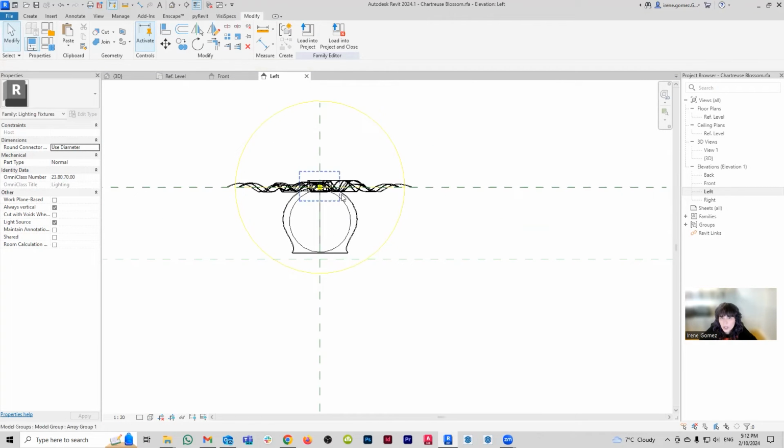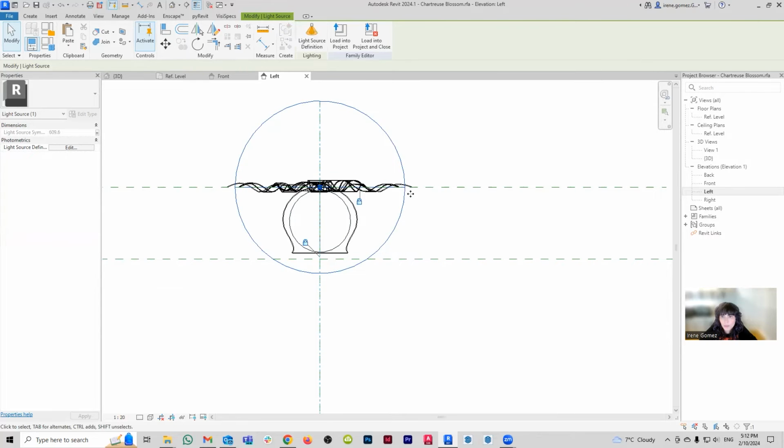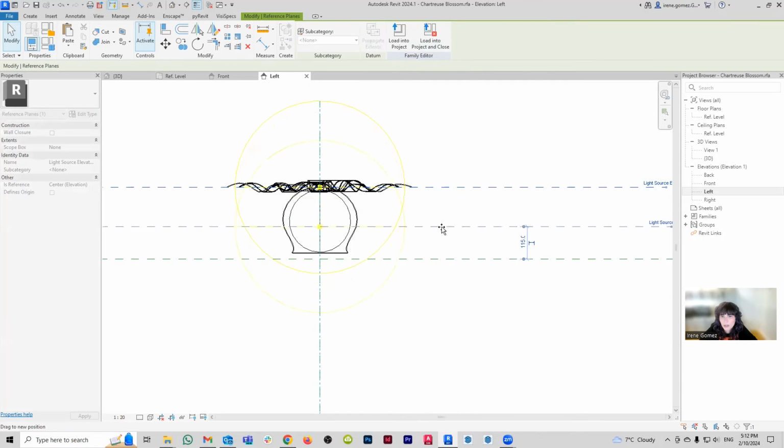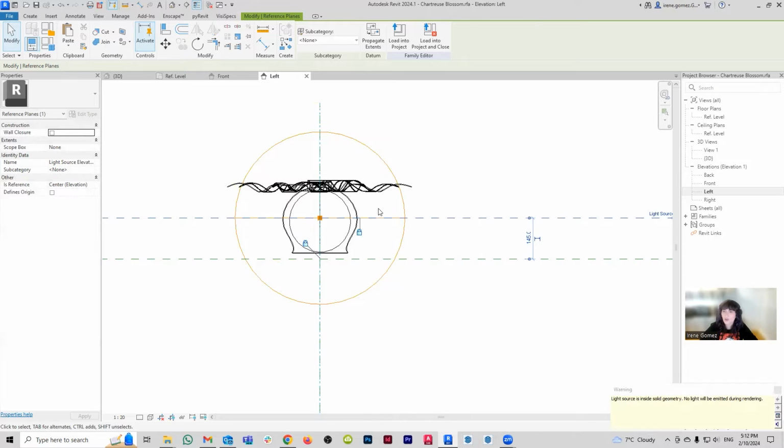One thing that I do want to do is move it down. So I'm just going to drag this down a bit. There you go. I want it to be more like that. Now you're getting this message, which is basically telling you that the lighting source is inside geometry. Don't worry about this. I mean, you do have to worry about this, but think about it this way. This message is simply telling you to be aware of the fact that lighting sources are sensitive to geometry. So if your light source is inside of a geometry that has a material applied to it that is solid, light will not be able to go through. So the rule here is that a light source can be inside of geometry as long as that geometry is either transparent or translucent, so it will allow the light through. And that is the case here, so I'm not concerned.